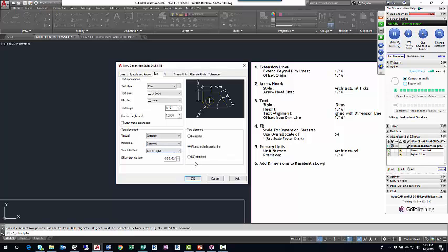This one's a little weird. At the very bottom of your dialog box, you have this 3/32 of an inch high value. If you click the arrow once, twice, you don't see 1/16. It just zeroes out. But if you click up once, it puts you at 1/16. However, you could just swipe over it or highlight it and just type in 1/16 or however you want to do it. And that's it for the text tab.